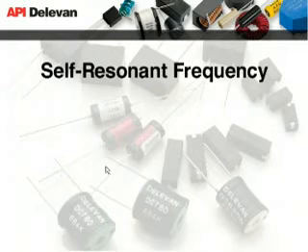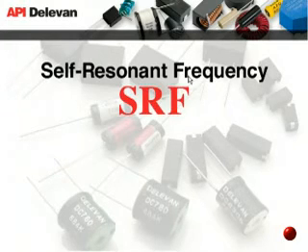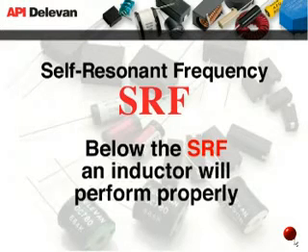The self-resonant frequency, or SRF, is the point where an inductor will act as a pure resistor, with no inductance and no capacitance. In actual inductor applications, the SRF is a much more important value than the test frequency, because the test frequency is only a guideline for assessing the suitability of one inductor over another. The self-resonant frequency is the limit above which an inductor is not normally applied.